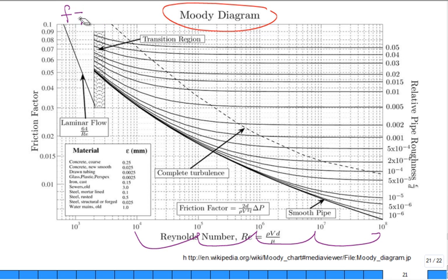Somebody comes in and they say, I calculated the friction factor, it's 4 times 10 to the minus 6. What do you say? I don't think so. I think a pretty low value of the friction factor is about 0.01. So really, this arms you with a lot of information. If your friction factor is not in that range, be skeptical, because this covers a wide range of numbers.